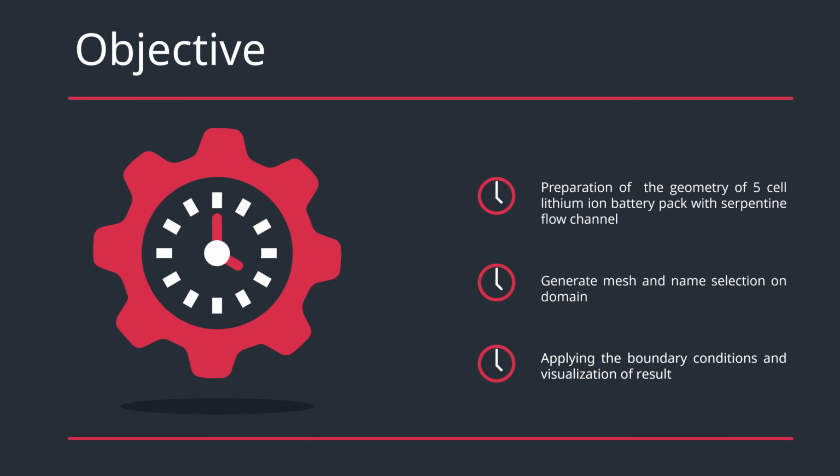How the geometry has been prepared is a very important, critical thing in order to proceed. Just take a look at this geometry first, how it is. Now first of all, if you see on the left hand side, I have selected one plane, that is ZX. So you can see on the ZX plane one sketch has been drawn. The purpose of providing a sketch is to have a geometry which has some arbitrary curves, this kind of pattern. It is not possible with the primitives, and that's why a sketch has been prepared. So there is one motto behind it.